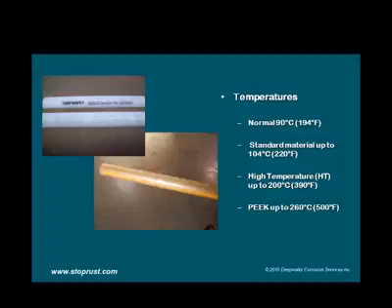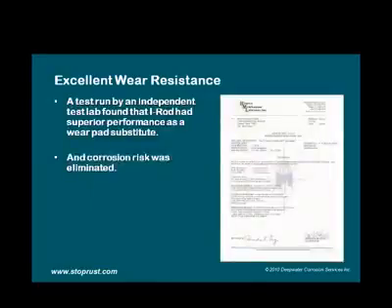We also have a high temperature version, HT we call it, which can operate up to 200 degrees Celsius or 390 degrees Fahrenheit. We also have a PEEK material, which is pictured there in the center. That can operate up to 260 degrees Celsius or 500 degrees Fahrenheit. However, at those temperatures, water evaporates just from the heat. Often those are used just for wear protection against the pipe, for movement of the pipe against the pipe support.